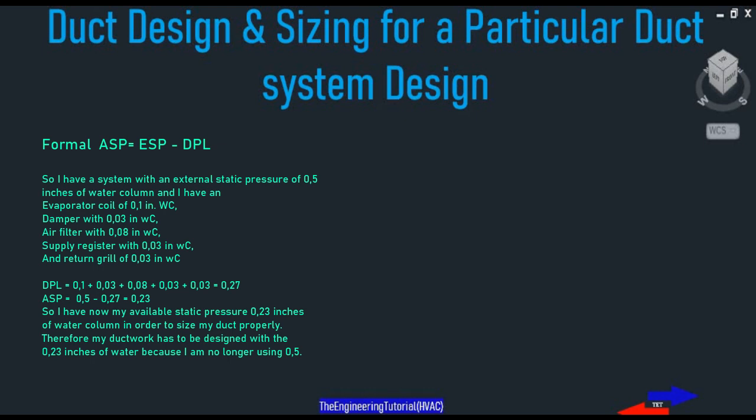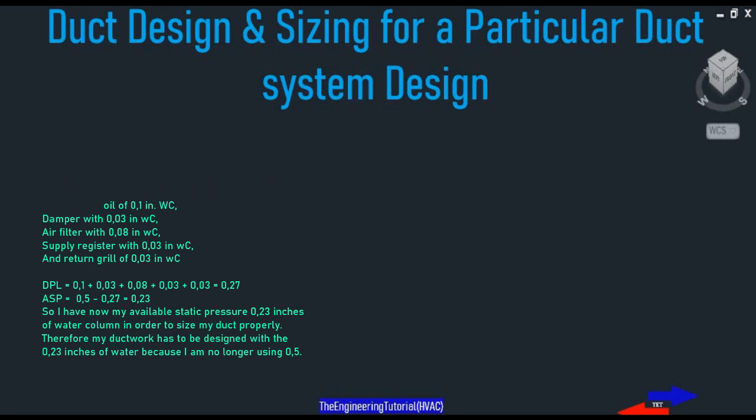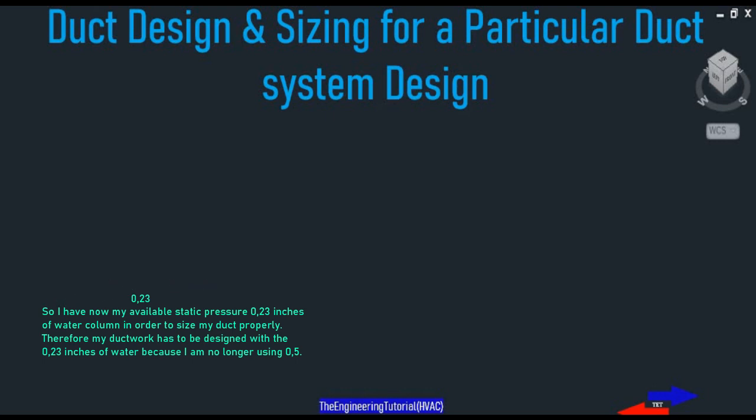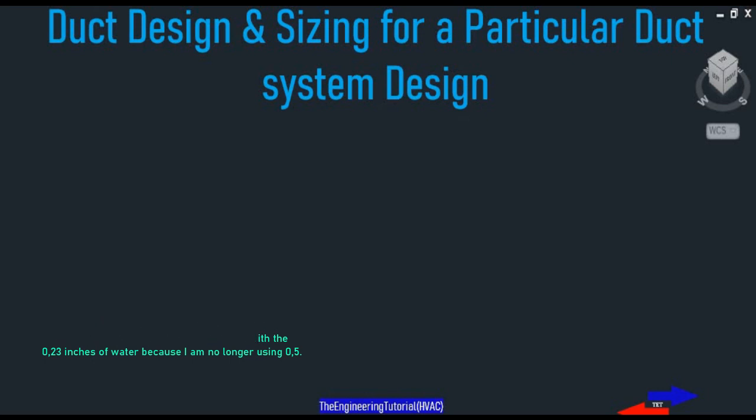So I have now my 0.5 minus 0.27 equals 0.23. So I have now my available static pressure, 0.23 inch of water column, in order to size my duct properly. Therefore, my ductwork has to be designed with the 0.23 inch of water column because I'm no longer using 0.5.